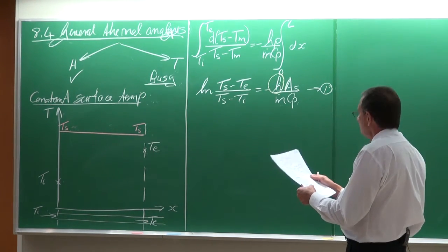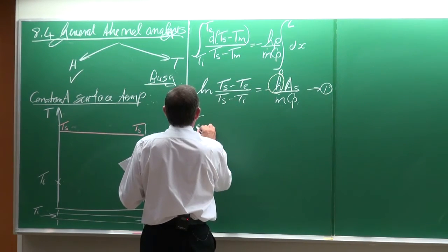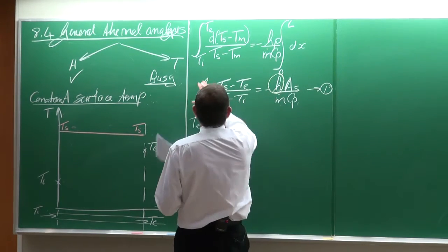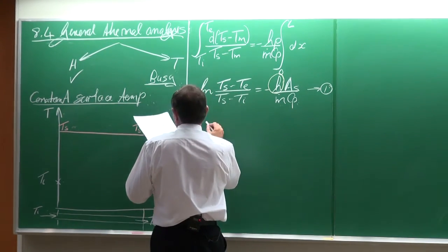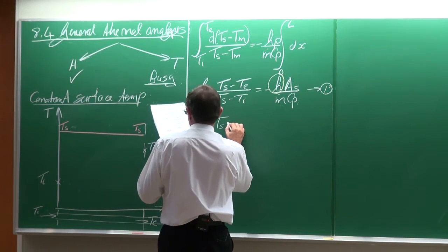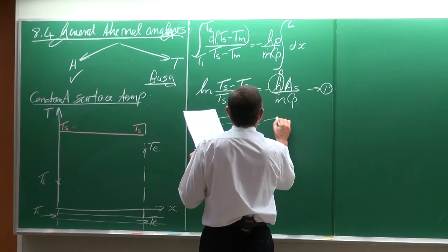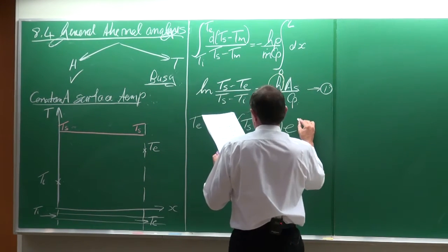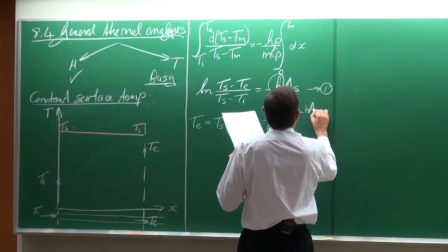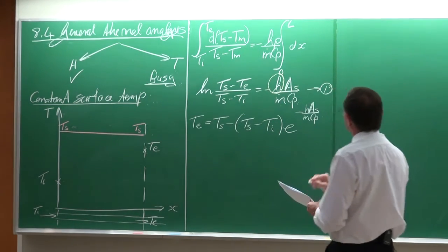important. Okay, so if we now go and solve the outlet temperature from this equation by just taking the e of this, then we get rid of the ln and making it neat, then we can write that the outlet temperature is equal to the surface temperature minus Ts minus Ti e to the minus h As divided by the mass flow rate and the Cp.